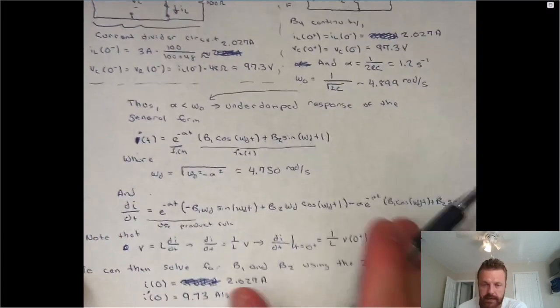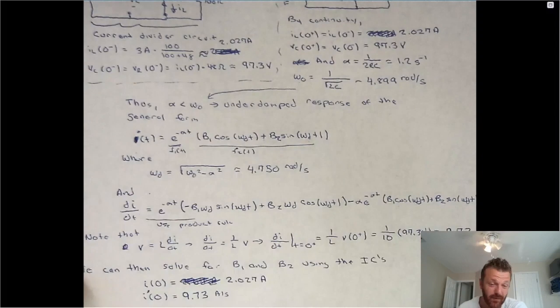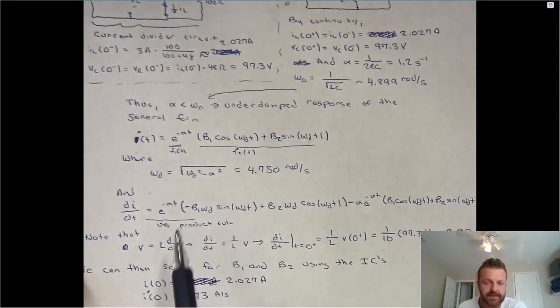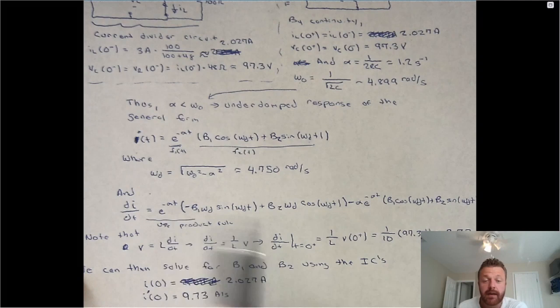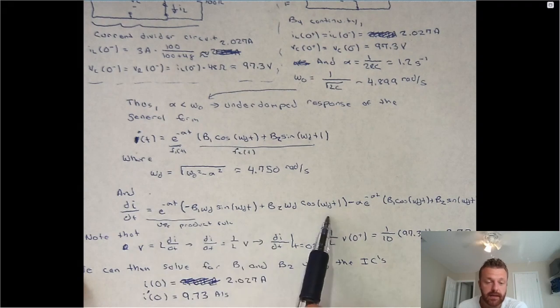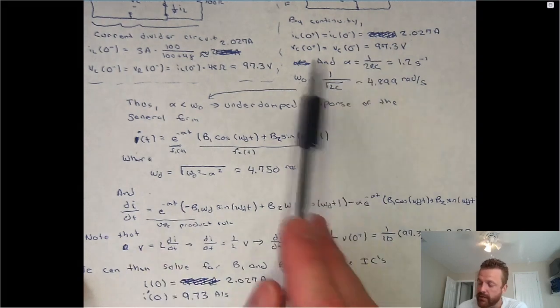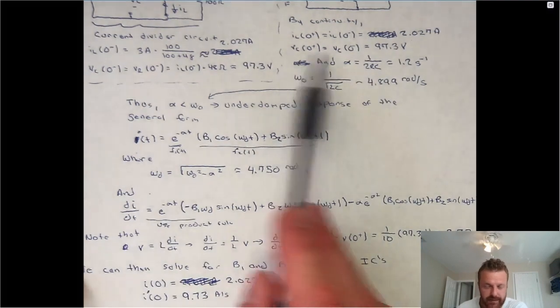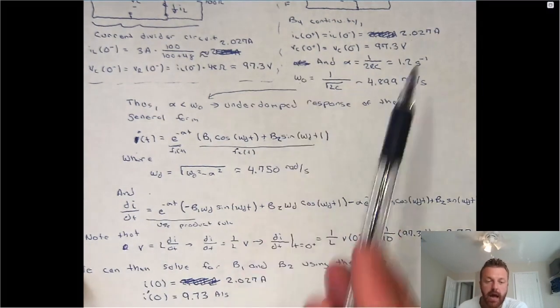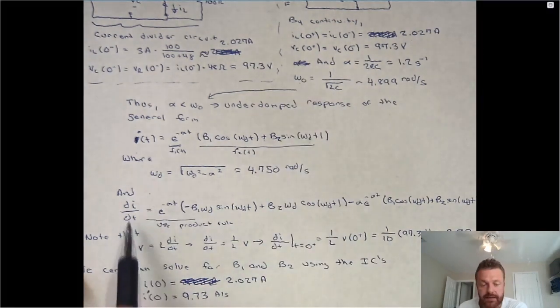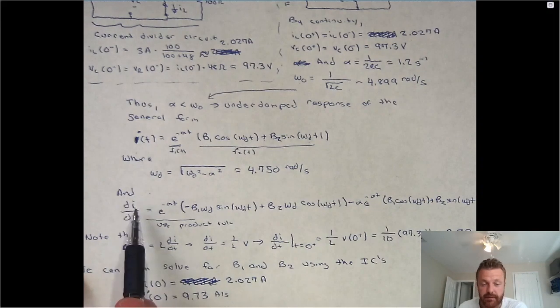Now this looks really intimidating, but remember the initial conditions are enforced at 0, and all of these functions have simple behavior when their arguments are 0. The exponential of 0 is 1, sine of 0 is 0, and cosine of 0 is 1. So how will we actually relate the quantities that we have, which are the initial voltage across the entire circuit or the capacitor, to this quantity that is the derivative of the function that we're solving for?